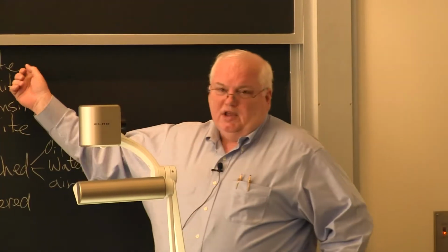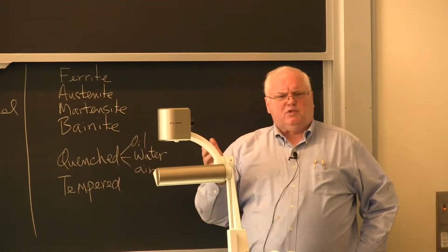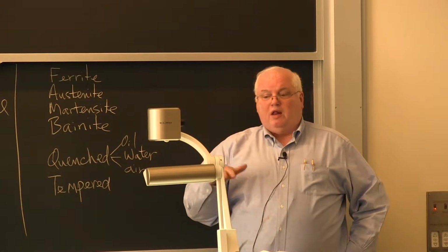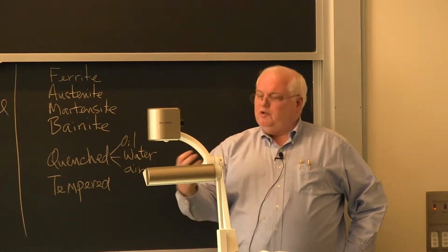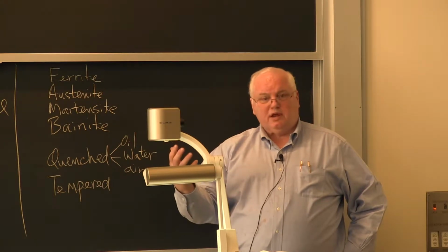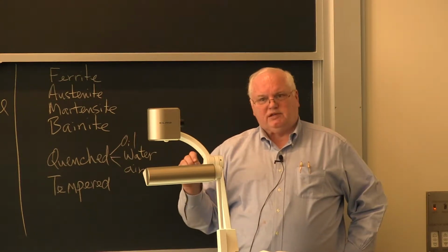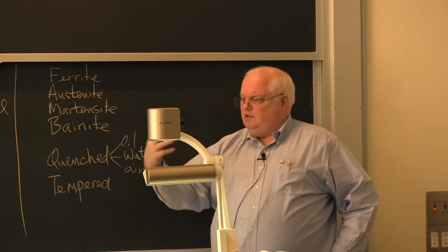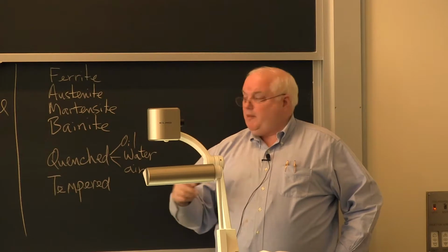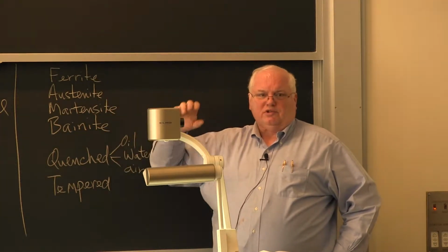Anyway, so Henry Sorby in England was a petrographer. He said, what if I do this with a piece of steel? If you polish a piece of steel, you grind it smooth and polish it, you'll end up with a mirror. Doesn't look like much of anything. Well, he had the bright idea to etch it with some acid. And when he did that, it sort of goes frosty when you look at it with your eye. Put it in the microscope and you can see grain structure. You can see the individual crystals.